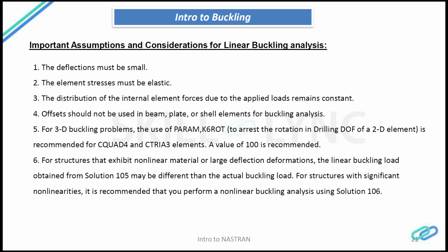So what are the important considerations that a stress analyst needs to keep in mind for the linear buckling analysis? First of all, when you say linear, it already represents that the material obeys Hooke's law, and the stresses are well within the yield point, within the proportional limit, so the material behaves linearly.